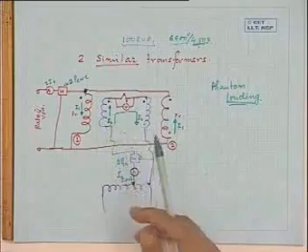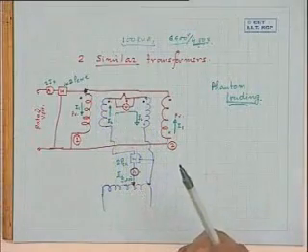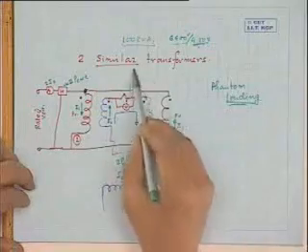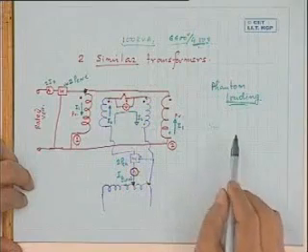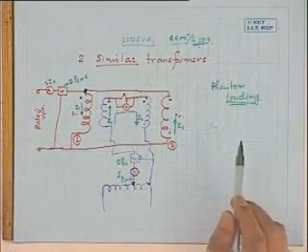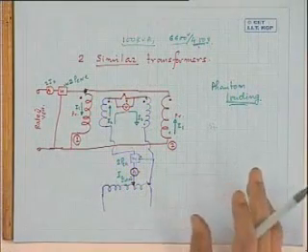And also you are testing how the transformer will really behave when it is put in service. See, during the loading, you find whether the windings are capable of carrying the rated current, whatever has been specified to us, and that also will be well checked without really loading the transformer, but making a scene that it is like loading the transformer, because primary and secondary windings are carrying rated current. Therefore, this Sumpner testing assumes importance.